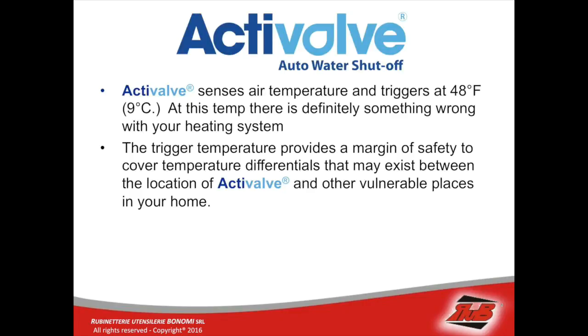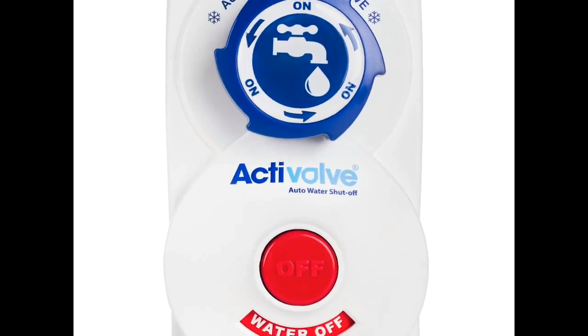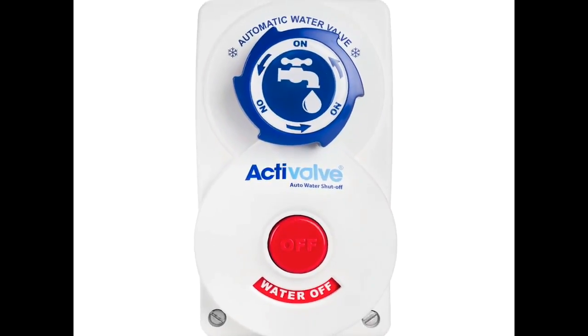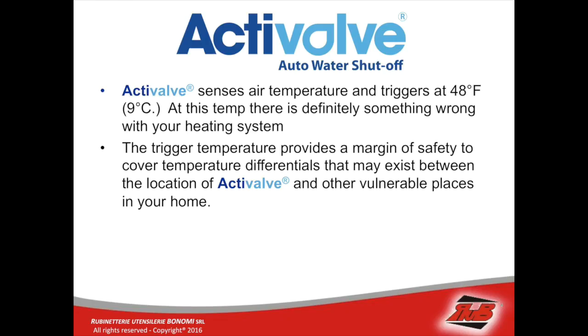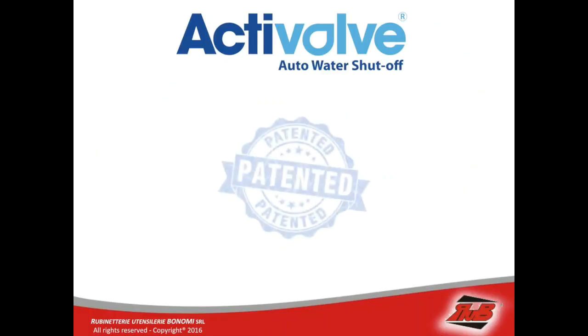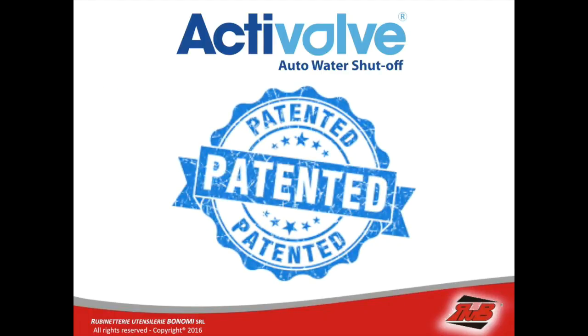ActiValve features an aerospace-grade thermal actuator that is designed to trigger at 48 degrees Fahrenheit. If your house temperature falls this low, there's something definitely wrong with your heating system. We designed the trigger temp set point at 48 degrees Fahrenheit so there would be adequate margin of safety to cover temperature differentials that may exist between the installation location of your ActiValve and other areas of your house that may be dropping in temperature at a faster rate. ActiValve is also a patented product.